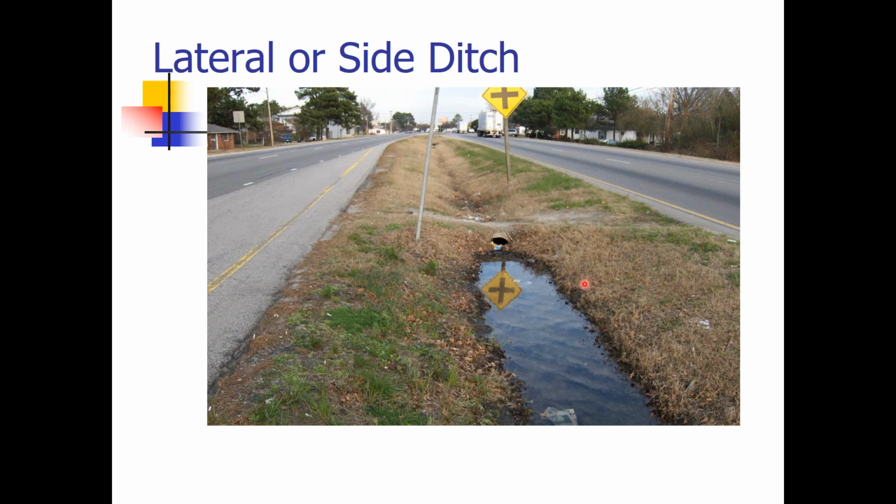Great. Yeah, definitely just put those in the question box where you told me hi earlier. And they're saying drive is blocked. Oh, let me go back up there. Sorry. Drive pipe is blocked, culvert clogged, standing water. Pipe looks like it is too small. Invert of pipe is too high. Pipe clog, not enough slope, clogged inlet and higher invert elevation.